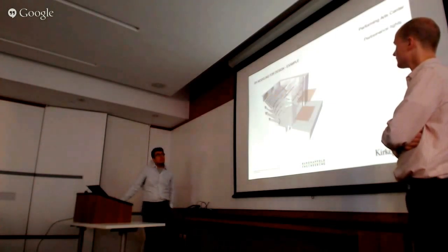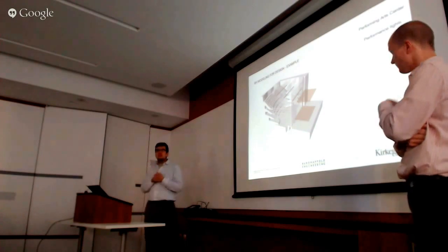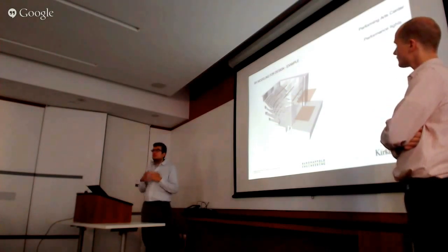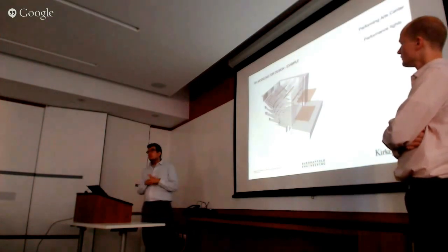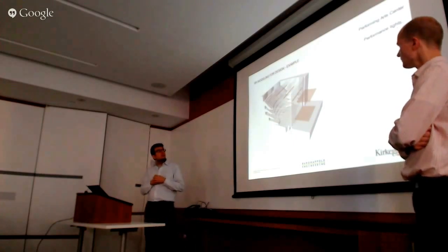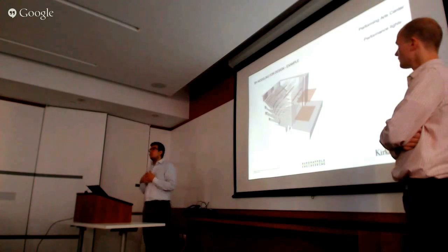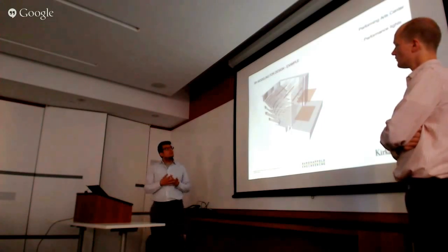But geometry is not the only thing. In a CFD model, a computational fluid dynamics model, the loads, especially for a sealed zone like this one, which had no exterior connections, were the single most dominating force. And one of those was the performance lights. They were so intense. The orange blocks are representing either where they are or where they are pointed, because there's a convective part of the light load and then there's the radiant part of the light load. We had to capture both.